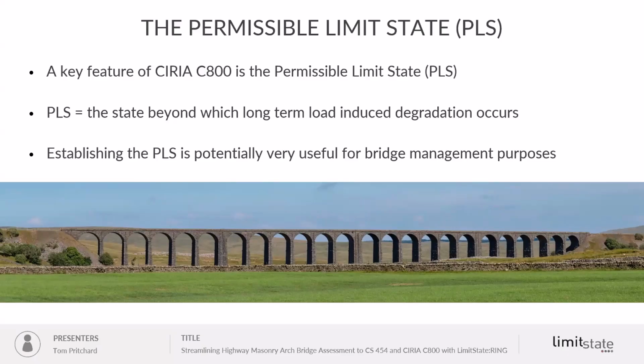We also know that the soil backfill significantly enhances the load capacity of a bridge by adding vertical dead weight to the structure and pre-stressing the masonry, as well as being able to help disperse vehicle axle loads and provide passive horizontal restraint. And these are all considered in an ultimate limit state analysis, as you would do in Ring.